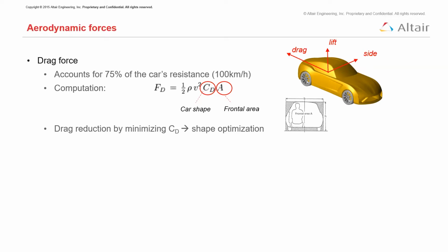Your drag coefficient is very much controlled by your car shape. So if you design a vehicle that's of that typical teardrop airfoil shape, you reduce the wake behind your car and therefore reduce the form drag, you're going to improve that CD value. There's other things involved in that, such as skin friction, but it is very much an all-inclusive value and very important to consider.